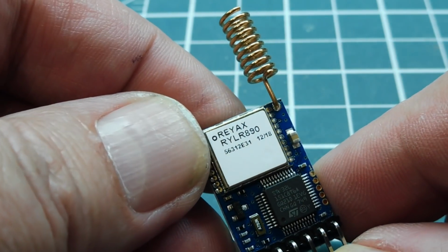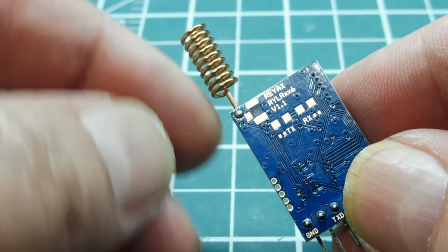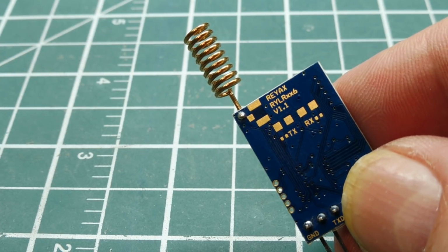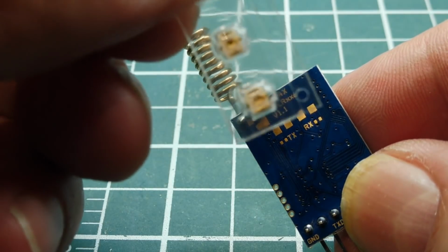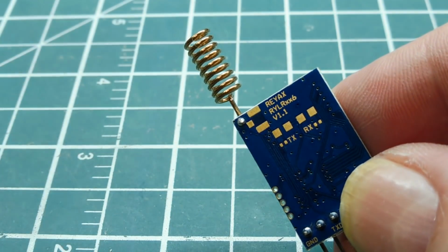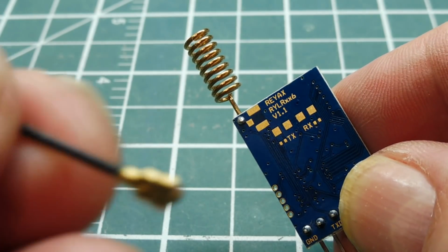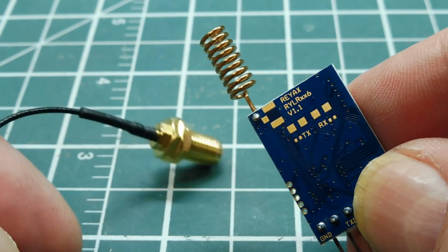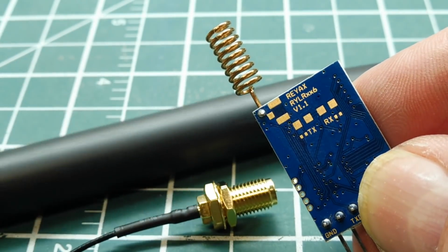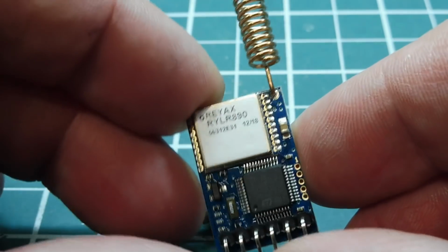Okay, this LoRa module comes with a helix antenna, and you could use it on your bench for testing. It works out okay, but if you want something a little bit better, if you look on the back, there are some solder pads, where you could solder on an IPX connector that goes on something like this. You'd solder on right there, then remove the helix antenna, and then you could get an IPX cable to SMA. Now you could hook up any kind of antenna that you want, and it will probably work out better than this helix antenna.